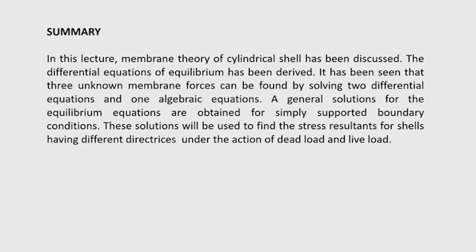What I mean is that it is a general solution, whatever be the radius of curvature and loading. Depending on the directrix, whether it is an arc of a circle, a semi ellipse, a cycloid or a parabola, whatever it may be, we can give the required quantities as input to this general solution. The required quantities are the radius of curvature and the values of x, y and z. After giving this input, we can derive the expression for membrane forces in the cylindrical shell for any type of directrix. There is no restriction that it should be a circular cylindrical shell; it may be a paraboloid shell. Any type of directrix you take, this expression can be used.